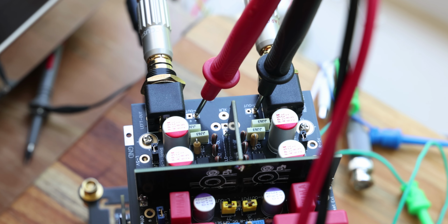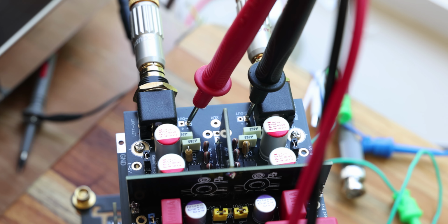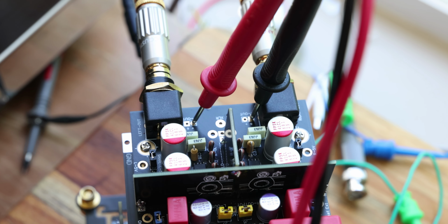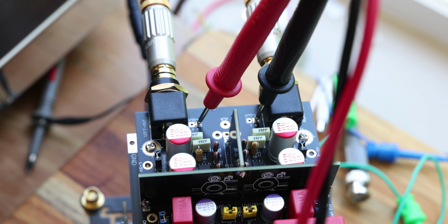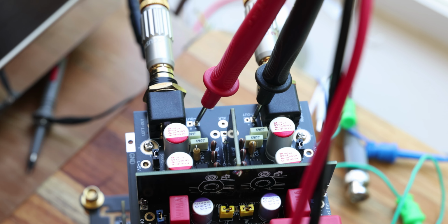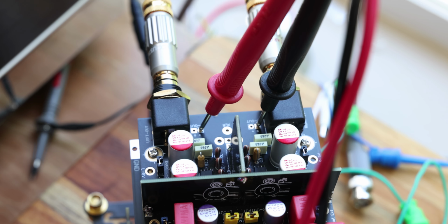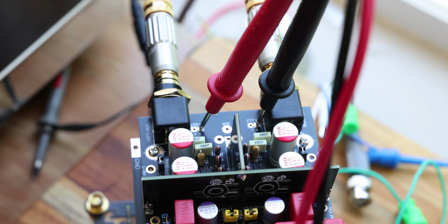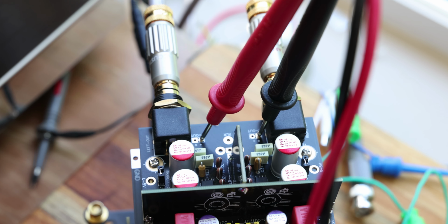To measure the DC offset, I suggest you put your probes one on each side. So you put negative on one side and the positive on the side that you want to adjust. That's the best way, because if you're trying to put them beside each other, it's going to be tight and it's hard to put the 2 probes together.